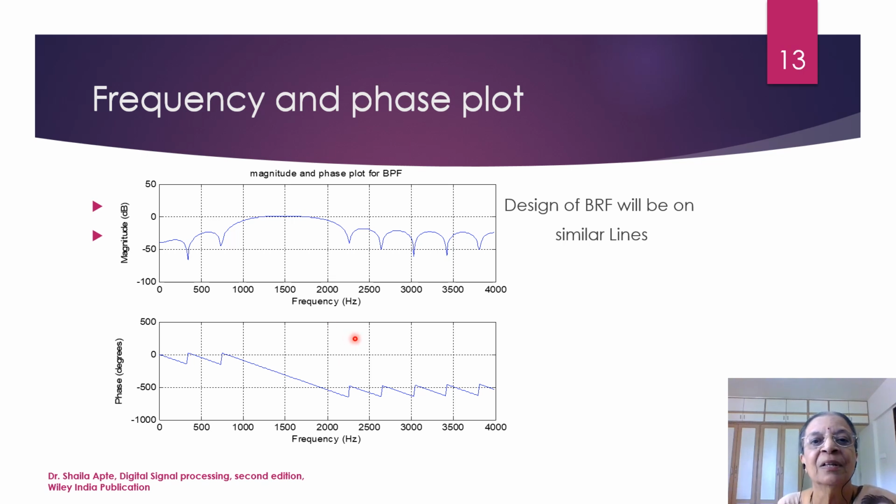Now, in these methods, what we do is we try to design the filter coefficients by considering the ideal response in the frequency domain. So we call it the brick wall response. That means we consider that it will come straight down when there is a stop band. Now, this sharp cutoff can never be obtained, isn't it? So we know that there will always be some transition width. The transition width can never be 0. So there will always be some transition width and there will always be some stop band attenuation which you can reduce further. So there is one more method that is possible, that is called the frequency sampling method.